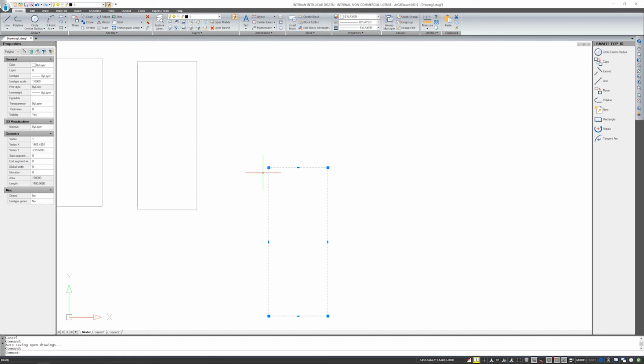You can assign the width of such a polyline, and you can also specify the width differently at different ends. For example, at one end, it will be a value of 1, and at the other end, a 5. It will simply be an arrow. Such elements are here to be defined in this property window, here in these places.